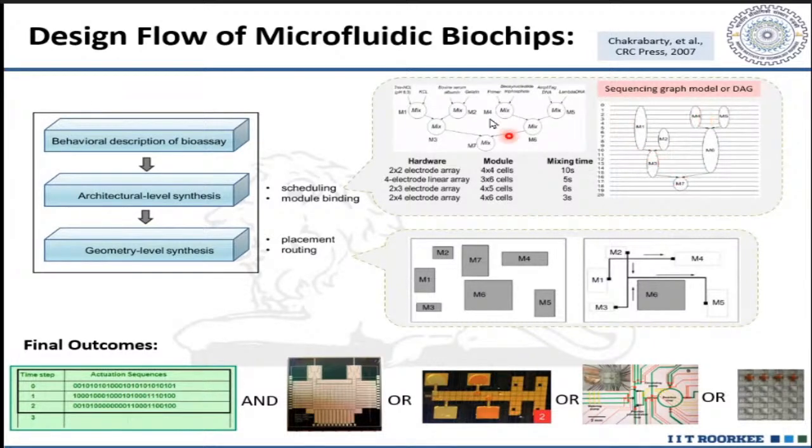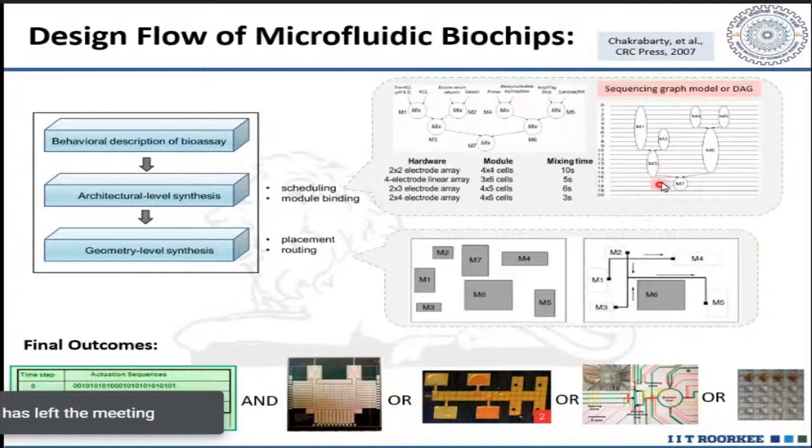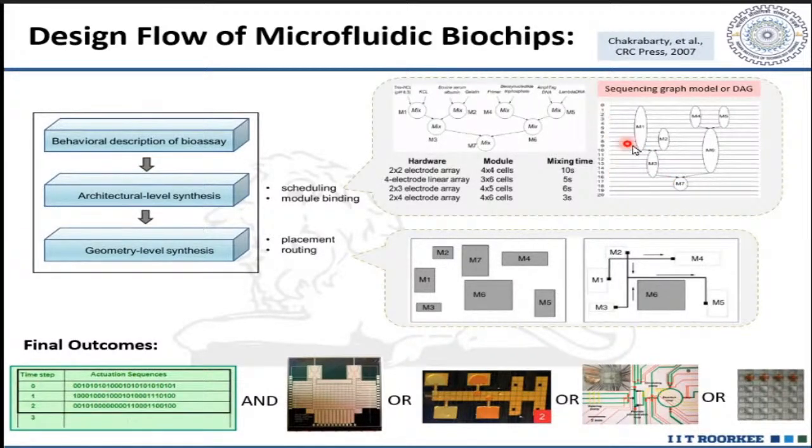So like this, your graph should be scheduled also. Each and every operation may take a different time to complete. That's why the scheduled graph will look like this, which tells that 0 is the timestamp where it starts, and then depending on the dependency, these directed edges, the graph is scheduled. And at the end, the last operation is finished at the 19th timestamp.